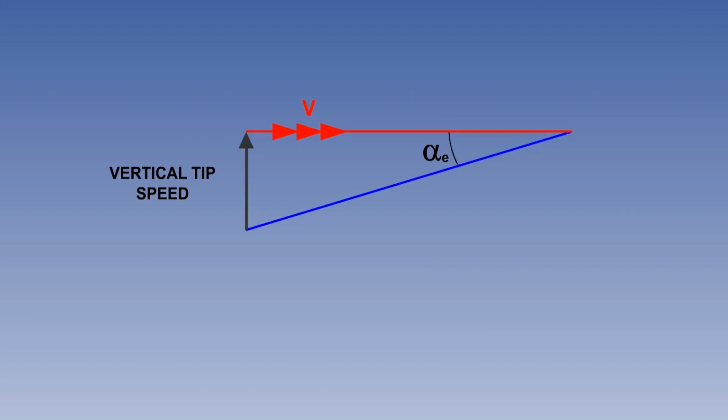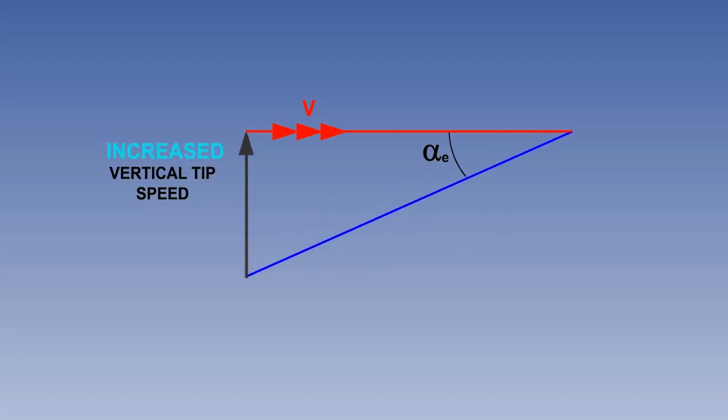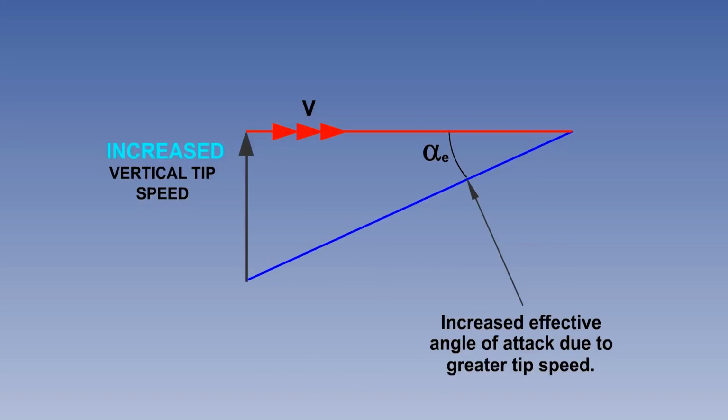The weight of the fuel counters the upward force of lift from the outer wing. A high aspect wing, particularly at low airspeeds, will suffer from a reduced rate of roll compared with a wing of the same chord but shorter span. The reduction is caused, only whilst the aircraft is rolling, by the increased vertical tip speed of the longer wing adding to the wing's forward TAS to cause a greater effective angle of attack with its attendant induced drag.